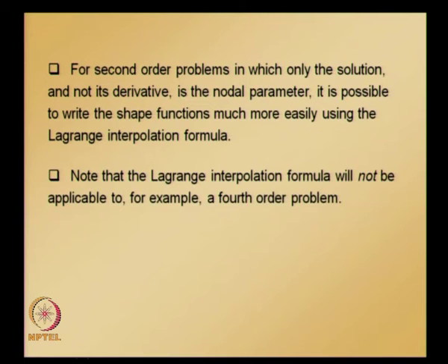So note that Lagrange interpolation formula will not be applicable to, for example, a fourth order problem, like a beam bending problem where we have both solution as well as derivative as the nodal parameters.